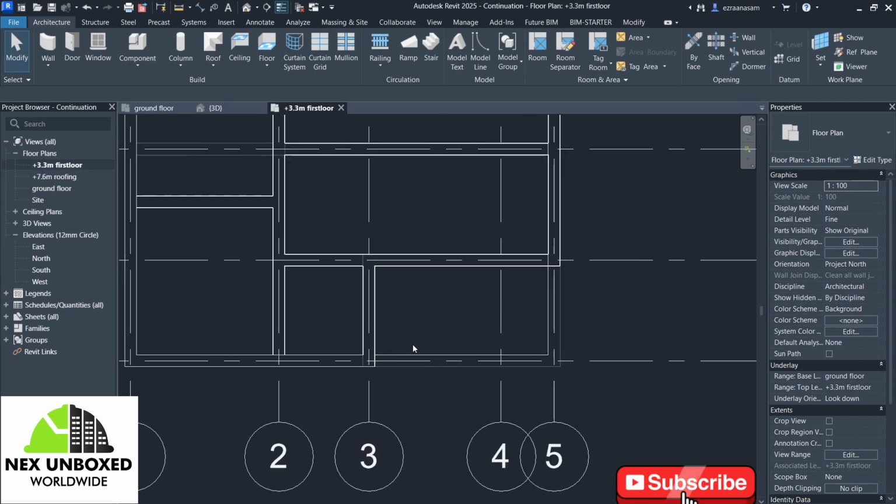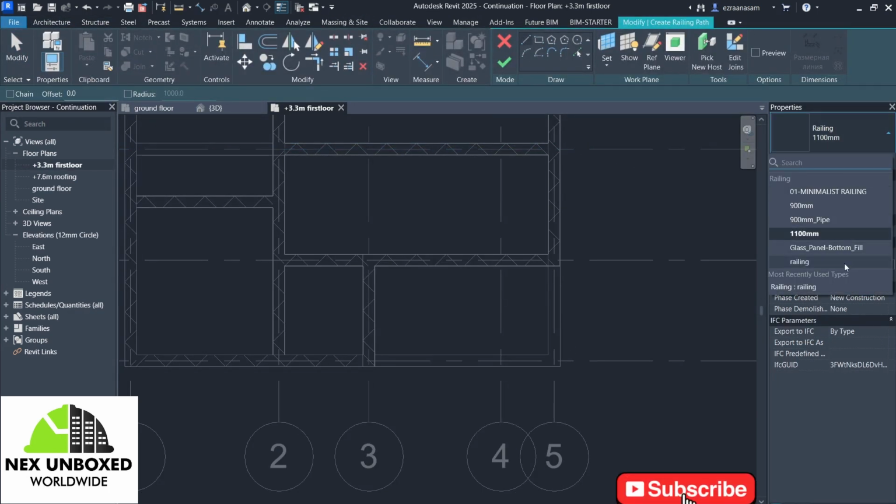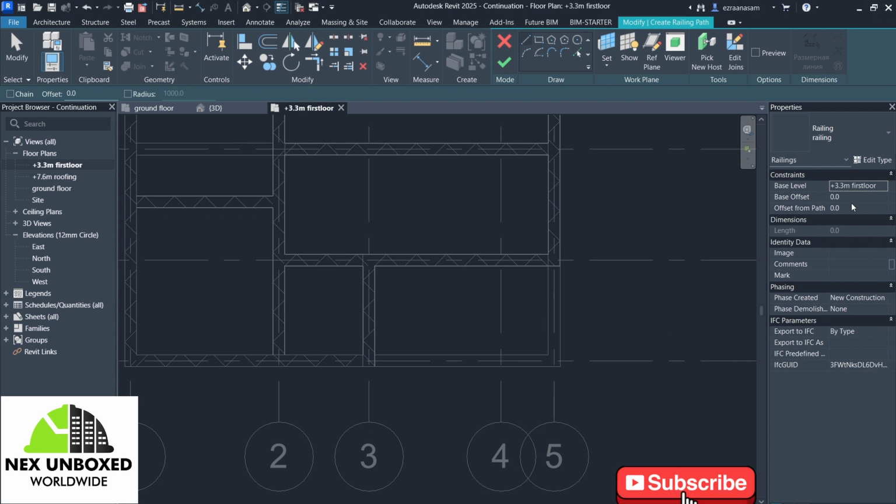Second floor. We need to put railing here, of course. And you come here, architecture, railings. If you click railing, railings will appear here. I have minimalist railing here. I will go with what? Railing here. I think it's a glass railing.